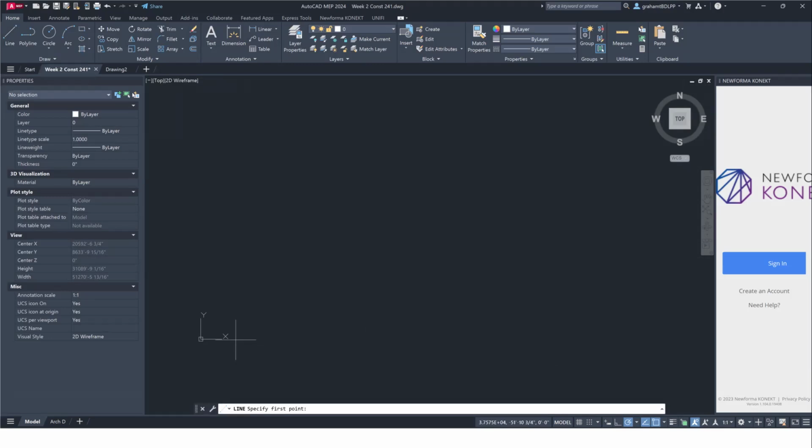And again, you may need to zoom way in. I don't know how far out it's zoomed. It may be zoomed out so that you're looking at it from like 35,000 feet up. So if you draw a line that's only 12 feet or maybe even only 3 feet, it might be hard for you to see it. If I drag up and it's wanting to snap polar, I'll say I want to draw it 3 feet and hit enter. And now I hit escape. I can barely see that little speck on the screen. I actually can't even see it.